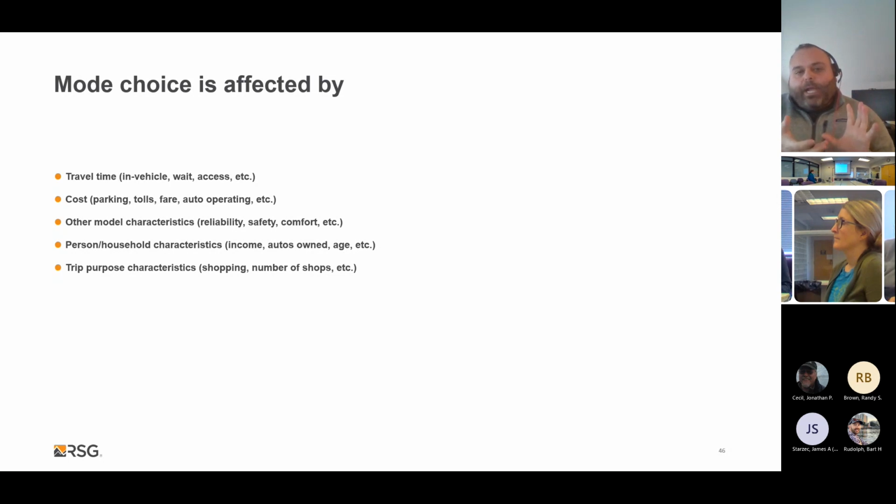If we look at the state of the practice of bike and pedestrian modeling, it's pulling it into its own separate bike pedestrian model and getting down into the details that you're talking about and estimating those things at those details. But you need to start at the household travel survey. So you need to say, okay, we want to do better bike ped modeling. In order to do that, we need to be able to collect information on, say, someone did a bike trip, right? What path did that bike trip take?